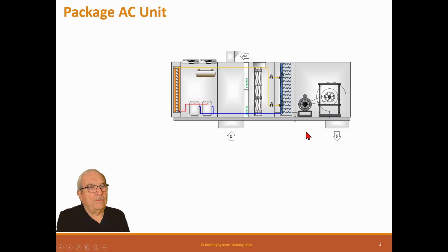So here's a standard commercial package unit. It has a blower unit to produce the air. Normally they're a draw-through arrangement, not always, but can be. And they go down to the space, up from the space to the return plenum through the filters. This one has an electric heater and goes through the evaporator coil. It has a condenser section, which, this particular one, has two compressors in it. It'll have condenser coils for those. It has receivers for the refrigerant. It has condenser fans, and it has an electric heater in it, and it has an evaporator coil.